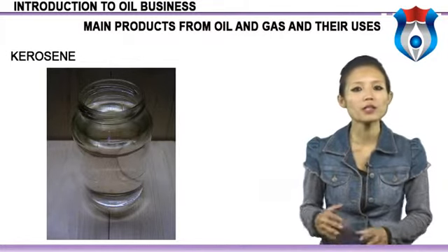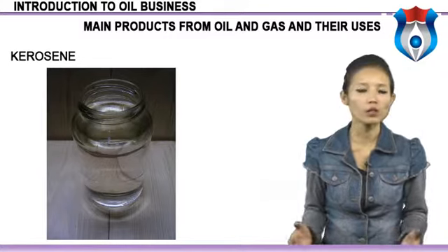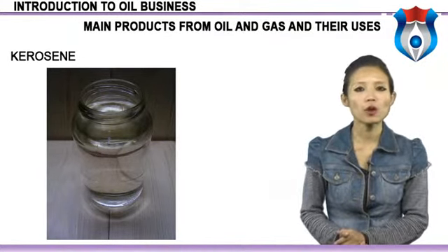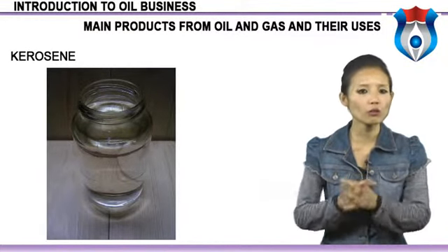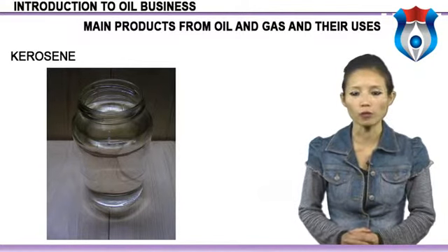The flash point determines below which temperature oil can be handled safely, that is without its fumes being spontaneously ignited. For kerosene, the flash point is considerably higher than for gasoline. This, together with its relatively low freezing point, is a main reason for its use as airplane fuel.